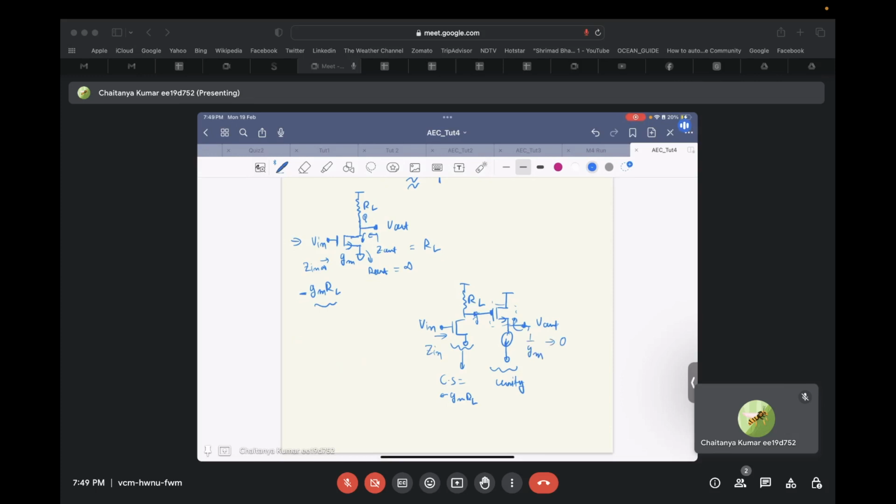So this is how you can make a VCVS with gain greater than unity, or gain other than unity for that matter. But again, the problem is that the gain depends on your transconductance GM, and the value of GM varies a lot with temperature and with VT, the threshold voltage variations. These things you don't want in your circuit.